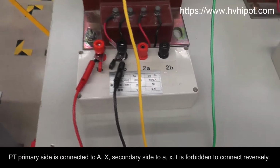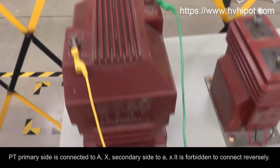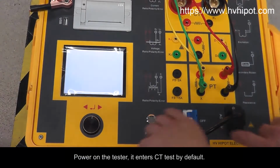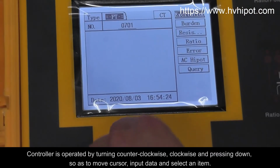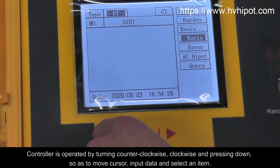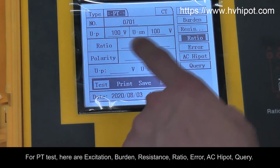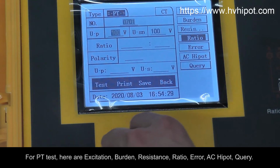PT primary side is connected to AX, secondary side to ax, it is forbidden to connect reversely. Power on the tester, it enters CT test by default. Controller is operated by turning counterclockwise and pressing down, so as to move cursor, input data and select an item. For PT test, there are excitation, burden, resistance, ratio, error, AC hipot, and query.